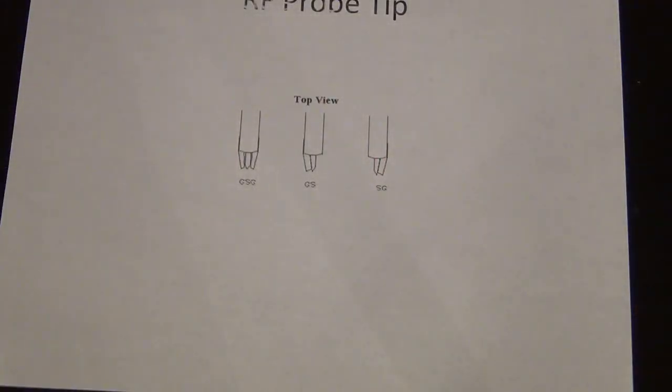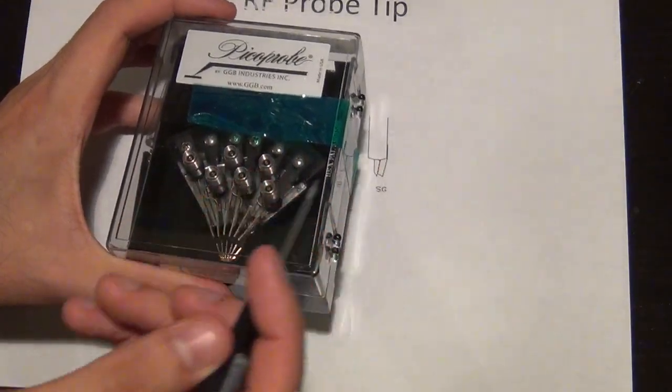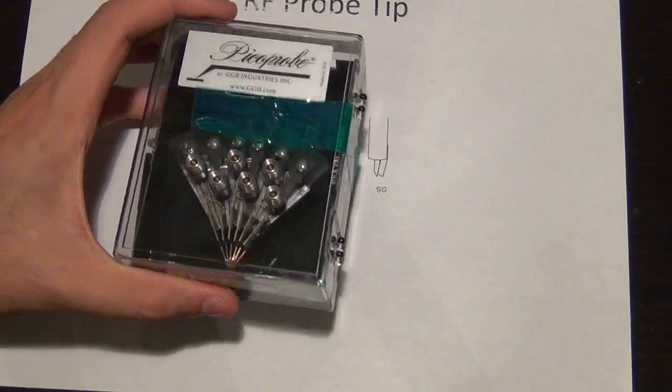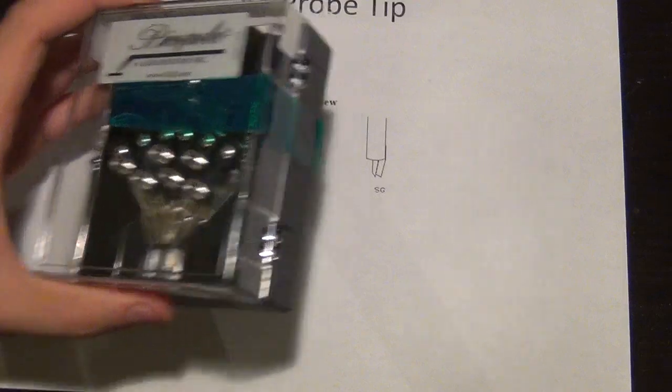So be very careful with these things, and make sure you use the proper connector and the proper cables, and you shouldn't put any weight on these. If you have a cable coming out of this, make sure the cable doesn't put a lot of pressure here. Tape the cable in place so it doesn't bend the connector, because these are not designed to handle much weight.